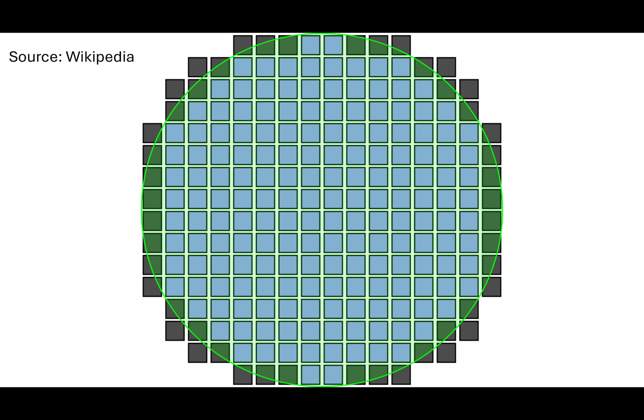And now let's say I considered this chip and found the distribution of resistors, and I found that the mean value of the resistors is, let us say, 1 kilo ohm, and then I have variations around that mean. Now let us say I take a chip from this particular section. Now if I find the mean of these resistors, it turns out this need not be the same.